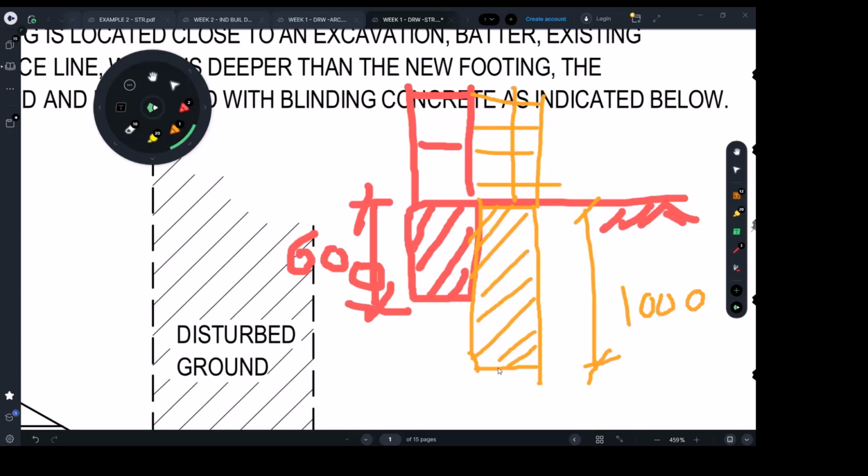Now, why can we not excavate? If you're going to excavate a trench hard against a neighbor's property, you're going to disturb their footing, and cracks may happen, and you're going to end up fixing it for them. So what else can be done? Any ideas? Any thoughts? We have options here, and we will be talking about them over the semester, but a quick answer here. Yes, definitely, we have to stop at the neighbor's footing. We have to stop here.